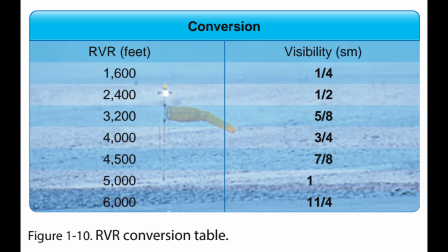An appropriate visual aid must be available to ensure the takeoff surface can be continuously identified and directional control can be maintained throughout the takeoff run. Appropriate visual aids include high-intensity runway lights, runway centerline markings, or other runway lighting and markings. With adequate visual references and appropriate OPSpec approval, commercial operators may take off with a visibility of 1600 RVR or 1/4 SM.